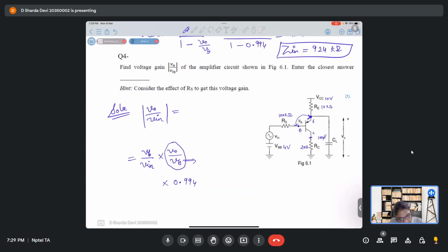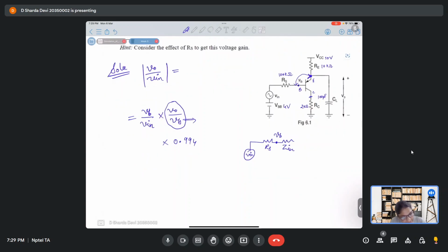What about VB by Vin? So Vin, it has RS, it has Zn, and here it is VB. So if I say VB by Vin, how can I write? I can write it as Zn upon Zn plus Rs, right? Yes, ma'am. So the same thing will come here.